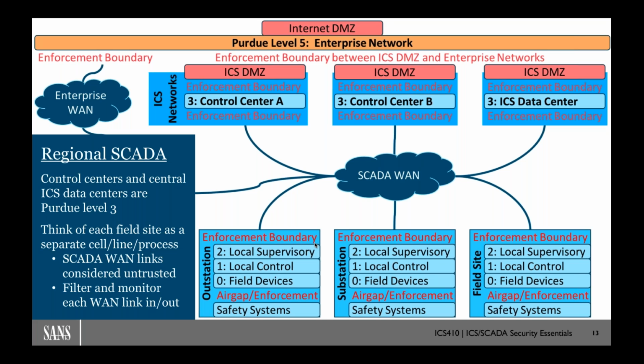You're correct. I didn't go into a lot of detail in the example I mentioned about the Tesla solution, but that's exactly how the Tesla solution works. These batteries have a little controller attached to them with an LTE modem built into it. So Tesla is literally dialing directly into these level 0 devices, right? That's the only way these devices are done. If you don't accept that, you can't deploy these devices. Tesla will not support a contract with you. So you basically have to accept that vendor's requirement to do LTE dial-in to level 0.